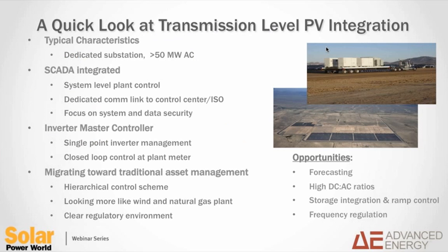These plants are under critical infrastructure protection, or CIP, compliance requirements, so definitely a strong focus around cybersecurity and some work going on to further refine exactly what those requirements are from a smart grid point of view. There's typically also an inverter master controller involved, and utilities don't necessarily want to go out and speak with 50, 100, 200 inverters. Maybe they want to speak with a single controller that can handle disaggregating the control functions to the fleet of inverters. And you can even perform closed loop control with some type of a plant controller at that point of common coupling as well.